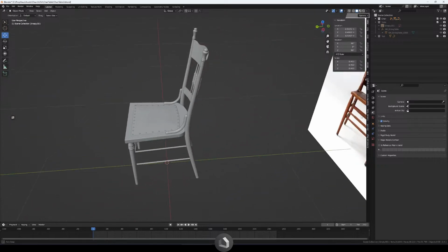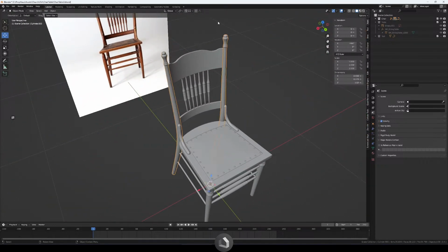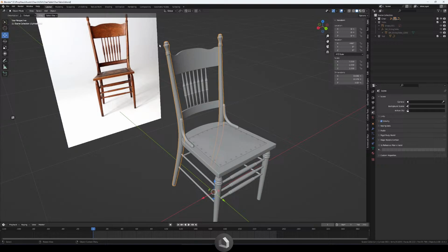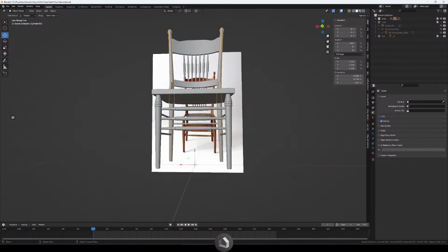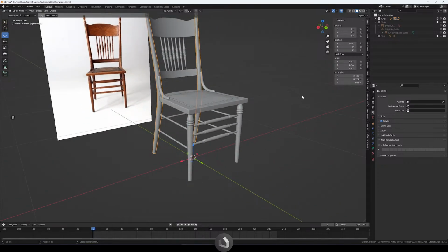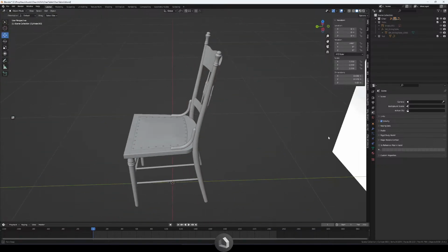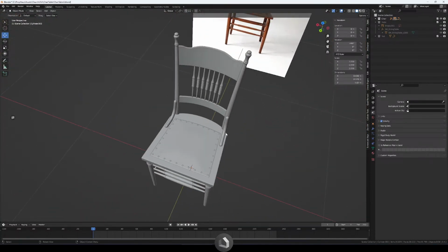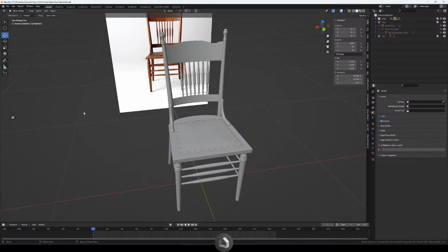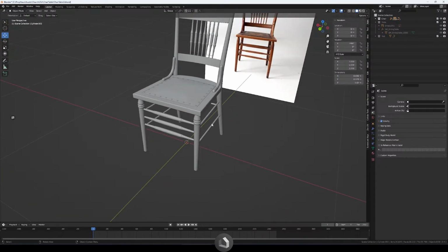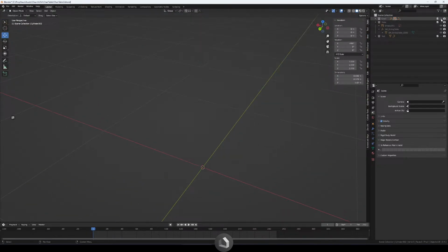I'm sort of curious if we should split some of the mirrored objects on here. Like we'll just bake one of these. We'll just have one of these in the texture, then we'll just mirror it over. Same with the legs and same with these spindles and stuff, just to save us some room on our texture sheet so we can have more high quality textures. I know there'll be repetition, but it will look a lot better. Yeah, I'm wondering if we should probably do that. Would be the wisest thing to do.